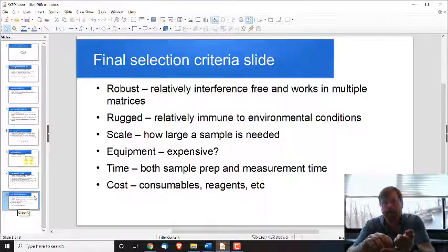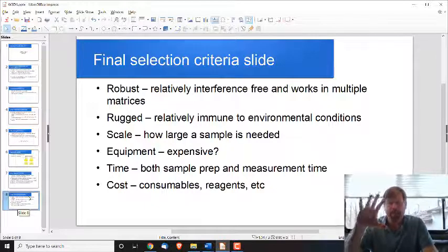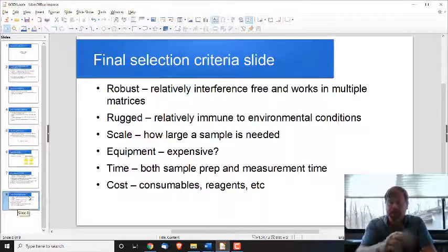Some tests, for example, chemical oxygen demand and biological oxygen demand tests for wastewater, are typically a little test tube you buy. You put your sample in. It's got the reagents in it. You put it inside the instrument that reads it. Then you throw that away, and you're done with it.